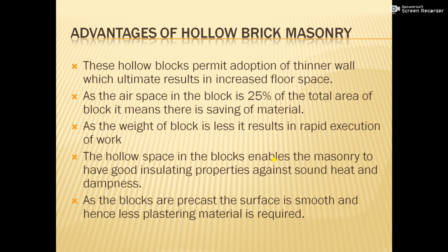Next, the hollow space in the blocks enables the masonry to have good insulating properties against sound, heat and dampness. The blocks are hollow inside and have some air space inside, and because of that these blocks act as sound resisting, heat resisting and also damp resisting. So they have a lot of good insulating properties.